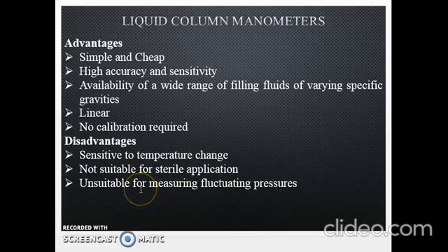Using the liquid column manometer in sterile application will lead to the introduction of impurities. Next disadvantage, they are unsuitable for measuring fluctuating pressures, because at each fluctuation in pressure we have to measure the height difference in the manometric legs, and that is why liquid column manometers are not suitable for fluctuating pressure conditions.